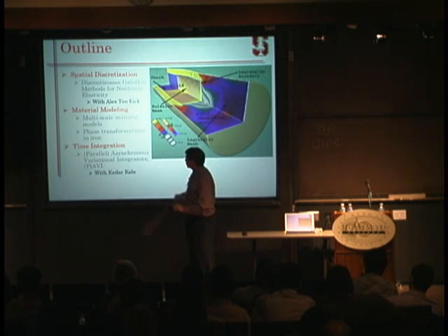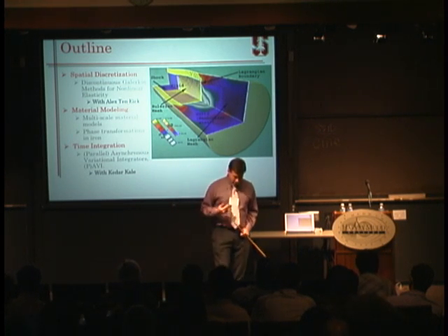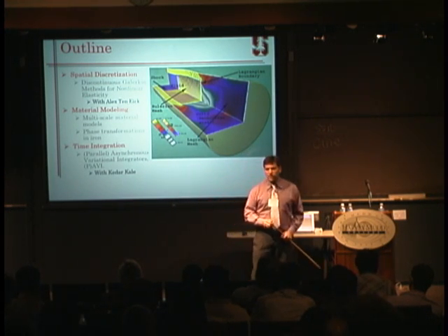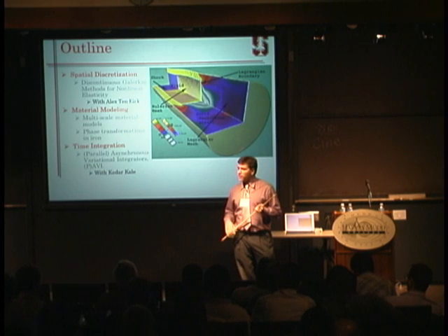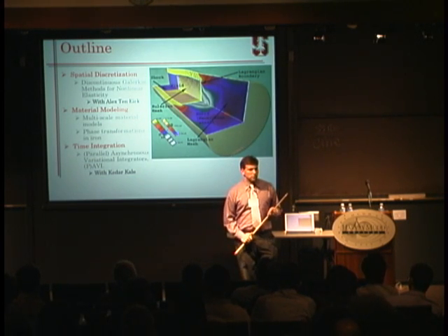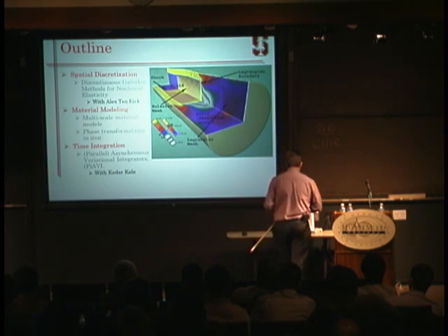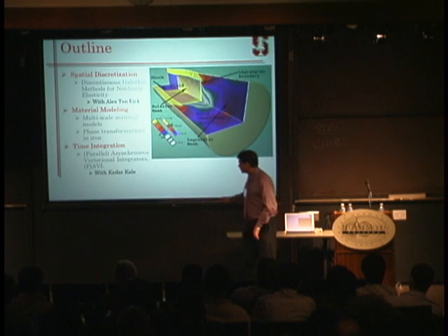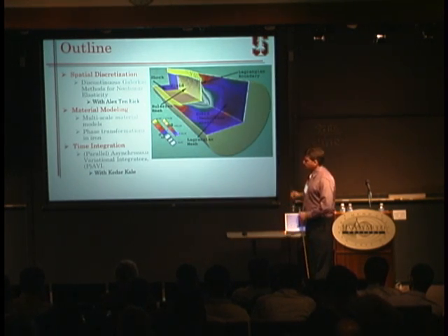And finally, I'm going to talk about time integration, and here I'm going to show a set of time integrators that essentially allow each element in a finite element mesh to have its own time step, and in addition to that, you have a very nice underlying geometric structure that gives you very nice conservation properties. I'm going to try to describe that. I'm going to include also the latest version of this, which is the parallel version, which is being finished by my student Kedar Kale.